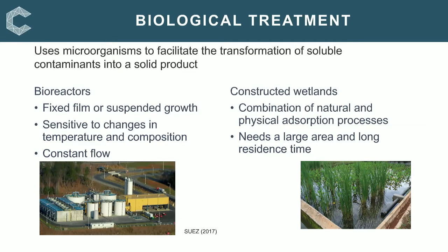The FGD wastewater does require some pre-treatment before it enters the bioreactors. This is commonly known as chemical treatment. But the microorganisms are sensitive to changes in the temperature and composition of the wastewater. A constant flow rate is preferred, otherwise the treatment efficiency is reduced.